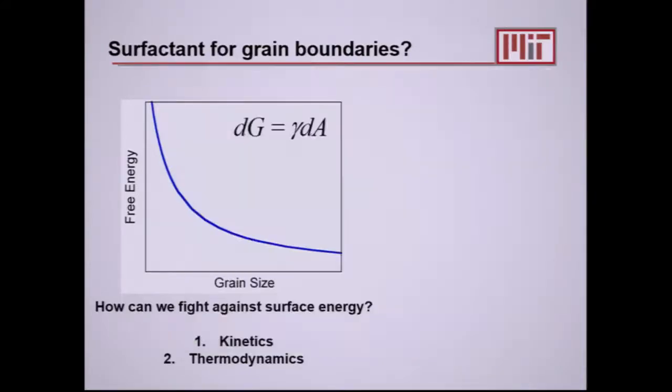The point here is that if you look at all the literature and how we address grain growth, we almost always are playing a kinetic trick, right? Material scientists usually are trying to slow down the motion of grain boundaries. They put in things that affect solute drag. They'll put in pinning precipitates. These are all, in essence, sort of kinetic tricks to slow it down.